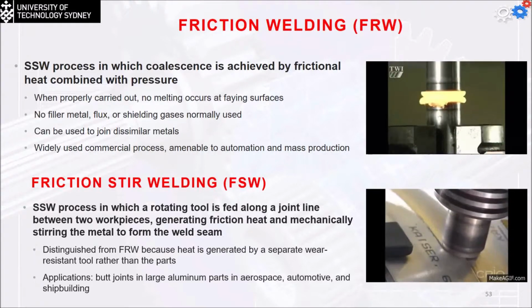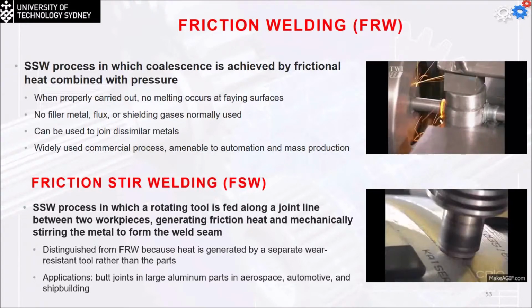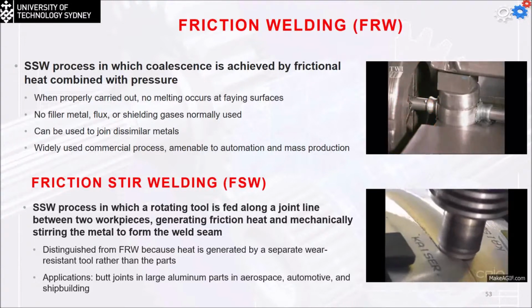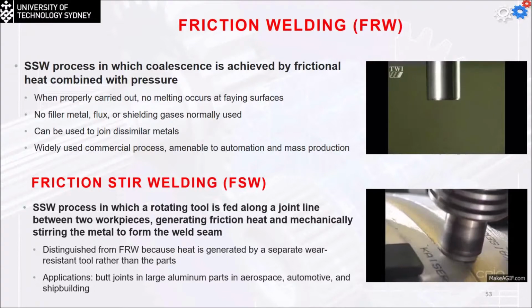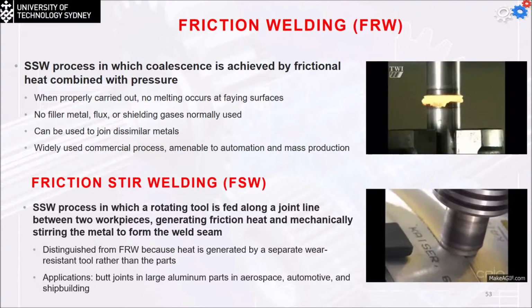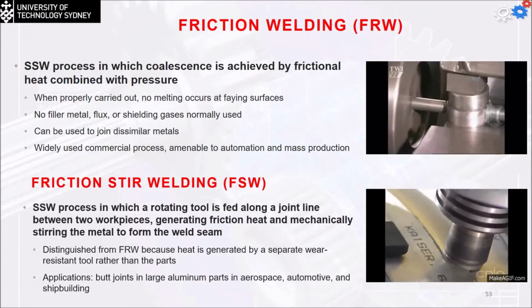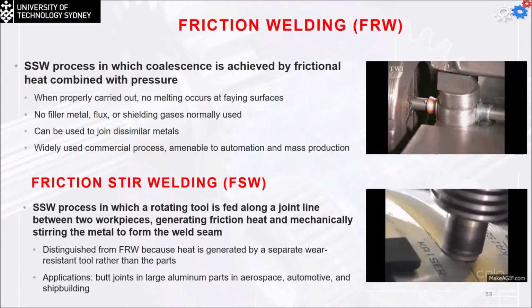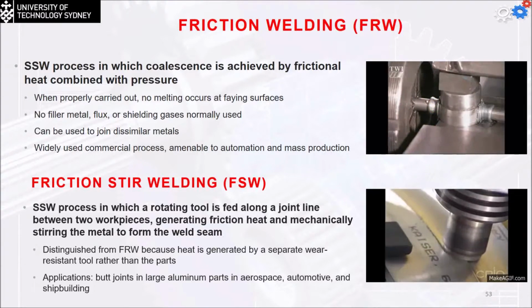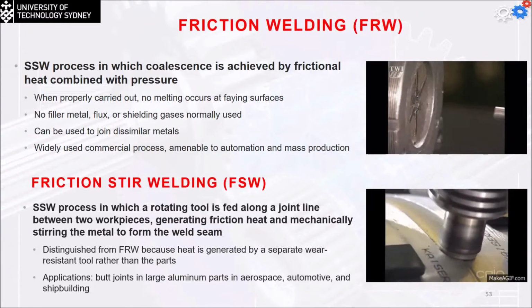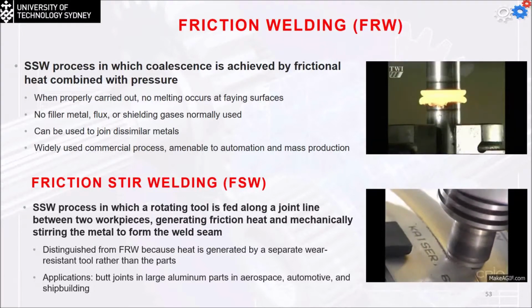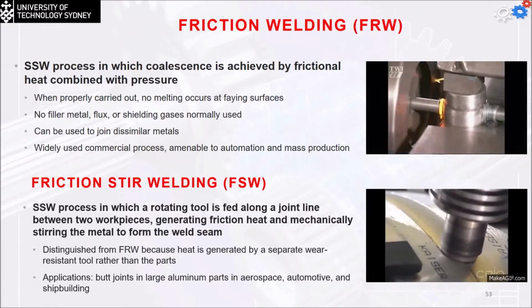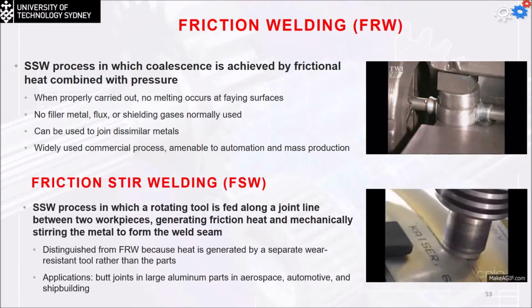Now, this is the last style, which is the ultrasonic welding. In the ultrasonic, we're going to have very high oscillation between the parts, and this will cause the friction to occur, and then the parts are going to be joined together. What's happening is that the two components are going to be held together at the beginning under high pressure, and oscillating shear stresses of ultrasonic frequency are going to be applied to the interface to cause the collisions.